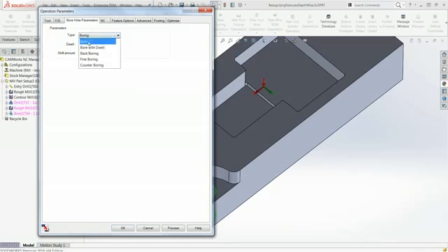The dwell would be for boring or boring with dwell, and back boring and fine boring have been added for the shift amount. So a value basically has to be specified for the tool to move towards the center line of the feature. This value can now be defined as that shift amount. And then boring and boring with dwell all have dwell settings in there as well. Again, this has to be handled by your post processor. So we have to just make sure that the post can handle that, and then you can go ahead and use the boring settings.